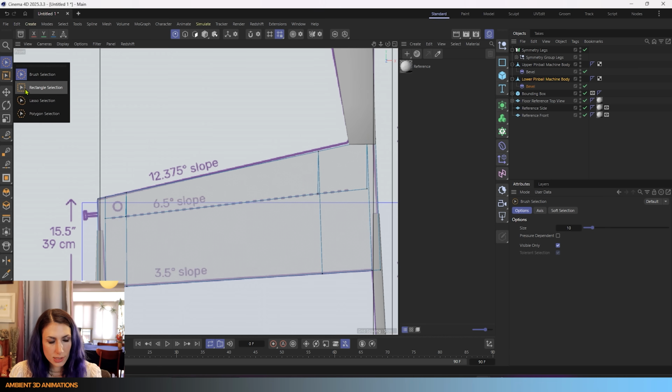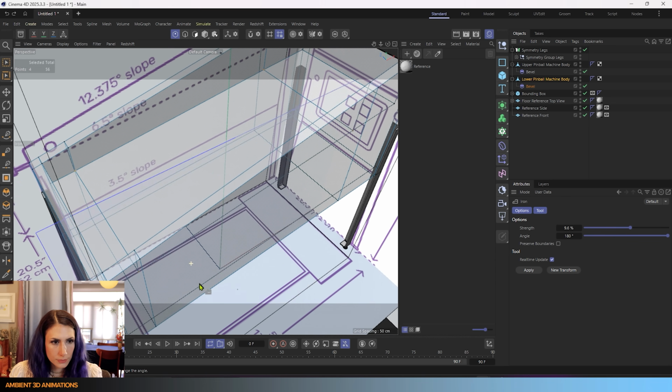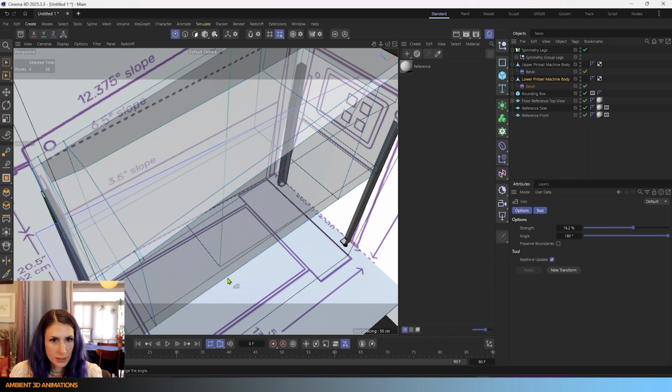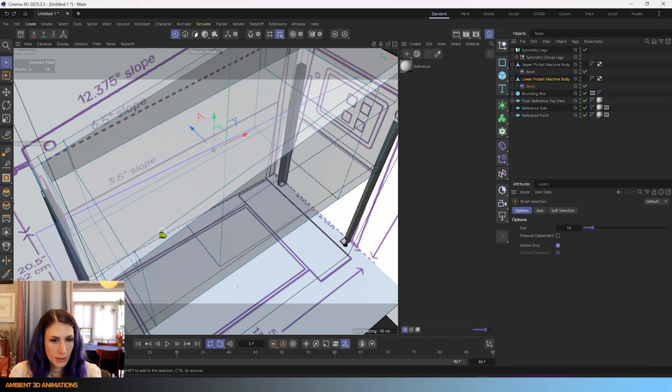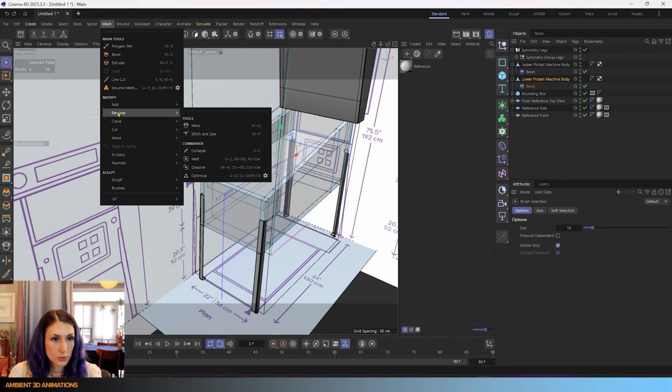And if we want to just double check that these are really nice and smoothed out, these points, we could even use the iron on them. But that might also bring them in a little bit, so it might smooth them out in both directions, whereas we would only want to smooth them out in one. We could also use the flatten tool. We haven't used that for a while. That's under the mesh menu.